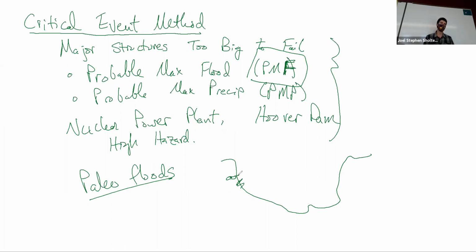And that tells you that water had been up there at some point in the last 10,000 years, assuming that this bedrock really hasn't changed that much. So you can go back and survey that and then use a hydraulic model like HEC-RAS to figure out the discharge associated with that water depth in a particular canyon. And then there are some pretty complicated statistical methods to figure out the frequency or probability of that event occurring. So that's one way you can do it.